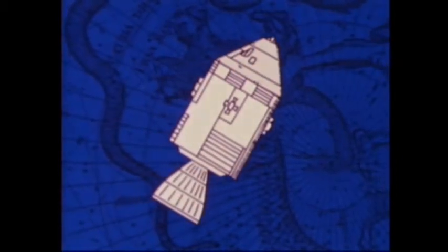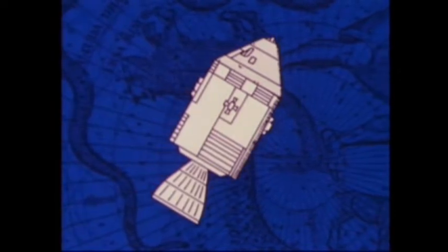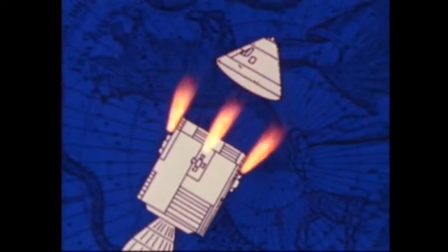Reviewing now, we see that before entering the atmosphere, the service module containing all but the entry oxygen and power supplies will be jettisoned, and the command module positioned in its trim alignment. It enters the atmosphere at the 400,000-foot level. At 0.05 G, aerodynamic stabilization begins. At the 2 to 2.5 G level, capture is considered achieved.